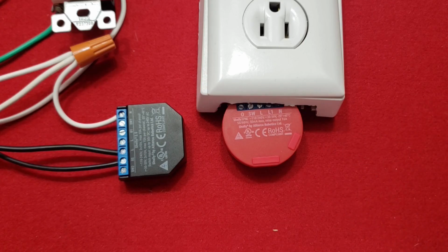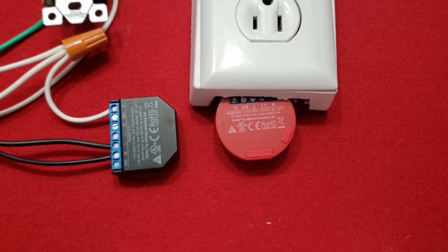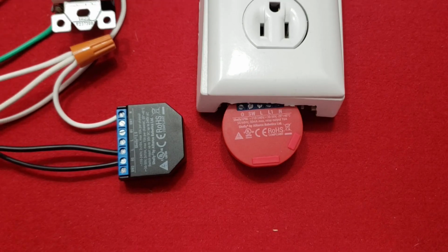The PM stands for power meter, or metering. There are a few versions of the Shelly 1 available, one without power metering, but why not just have it, and one that doesn't require a neutral wire, although this is not a concern of mine, so I've never used one. Wiring is very straightforward, as the devices are very clearly marked and come with very simple, easy-to-read instructions.